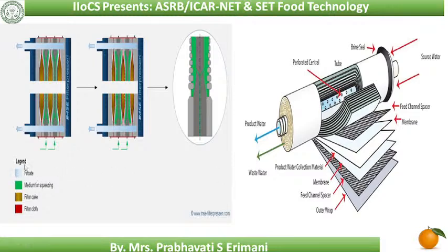This picture also shows the principle of membrane technology. Here you can see this color is the filtrate, and this green is the medium for squeezing. It is squeezing out, and here you can see the filtrate coming out. This is the filter cake, and the red color is the filter cloth. This is how the squeezing occurs.